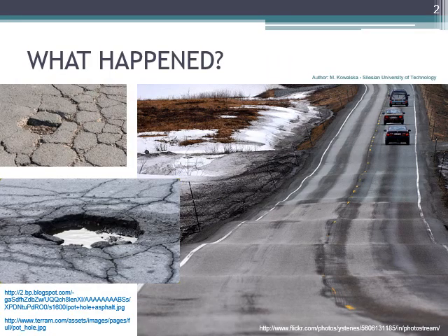Look at these photos. The one on the right was taken in Norway. The pavement damage that you see was observed along 80 kilometers of this road and occurred after a very cold winter. The photos on the left were taken in Poland, and it is actually a picture that we see every spring. They all show the effect of freezing and thawing of soil. The pressure that is generated there may be sufficient to lift road surface, pavement, but also some lightly loaded foundations.